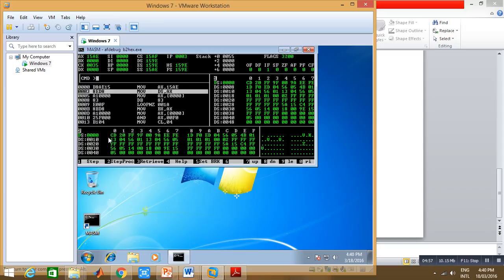Okay, first the data is loaded to the AX register, so 55 is copied to the AX register. I am ANDing with 0F to get the lower nibble, and to get the upper nibble I will just AND with F0H. Use the count in CL, count 4, which is loaded to the CL register, and rotate the content of AL 4 times to get the 0th position.